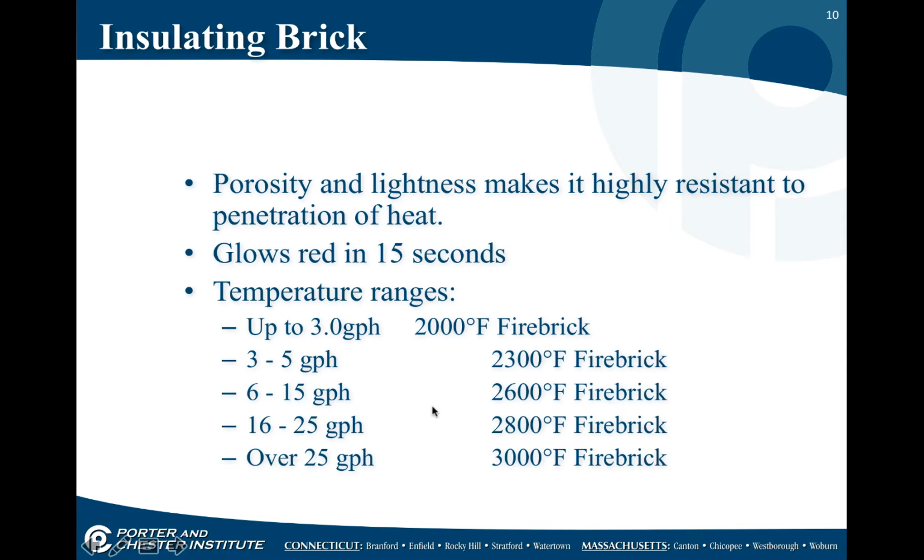Insulating brick: the porosity and the lightness makes it highly resistant to penetration of heat. It glows red in about 15 seconds. And it comes in different temperature ranges. Up to 3 GPH, we use a 2000 degree fire brick. Over 25 GPH, and again, this would be like in power plants and large commercial industrial water heating environments, we might use a 3000 degree fire brick. The ranges are based on the gallons per hour.